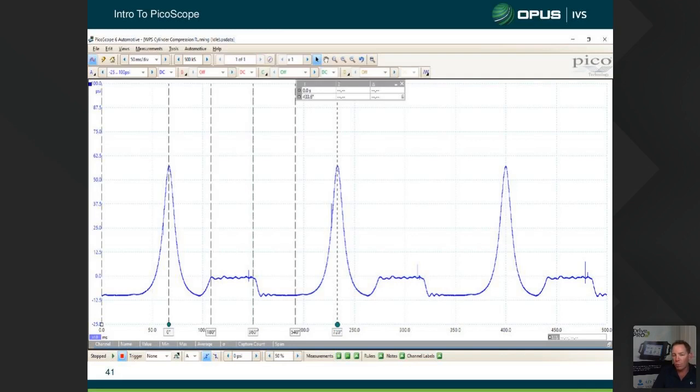I've put 4 of them in place simply by going into rules, clicking on that button, and then selecting times by 4 rather than times by 1. And because it's a 4-stroke engine, I've got 0 degrees there, and I've changed that value to 720 degrees. The reason I've done that, it basically allows me to look at a full 4 strokes of this particular engine. So I can see here as my pressure goes up in the cylinder, top dead center, compression number 1. So that'd be 0 degrees.